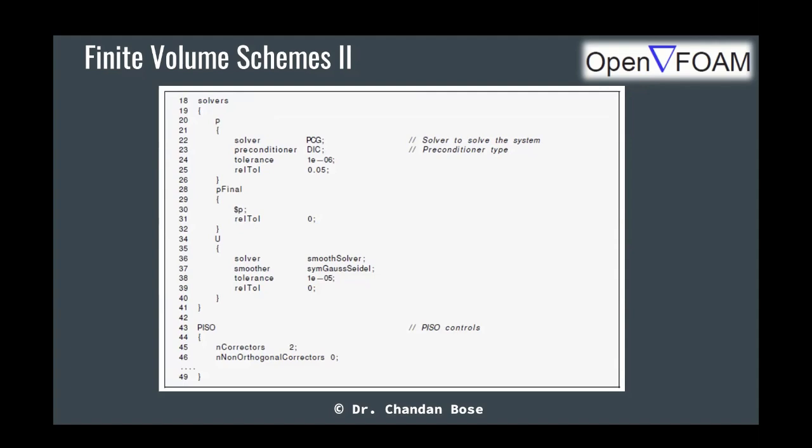So once you have the partial differential equation as your primary governing equation, you discretize using different discretization schemes of different orders of accuracy. And then what is the result that you get? How do you transform the partial differential equation to a set of different equations? So what is the nature of those equations? They are a set of linear algebraic equations. So these solvers here mean they are linear algebra solvers.